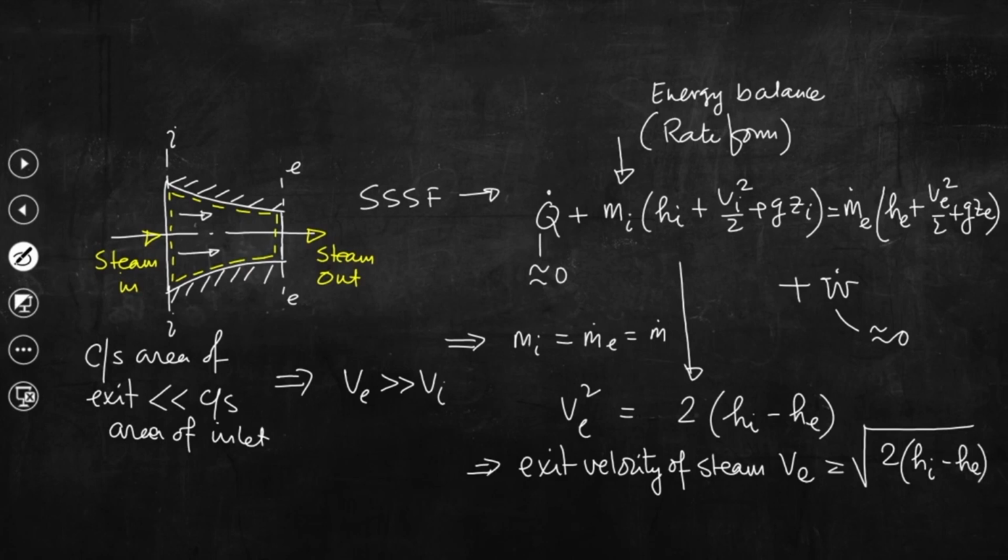So, try to understand the velocity of steam at the exit of the nozzle is nothing but the total enthalpy drop across the flow nozzle. Next is, so if we express this enthalpy drop in kilojoule per kg, this velocity would be coming out 44.72 delta h power half meter per second.